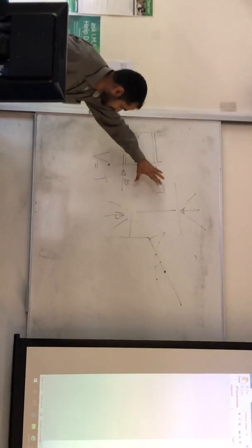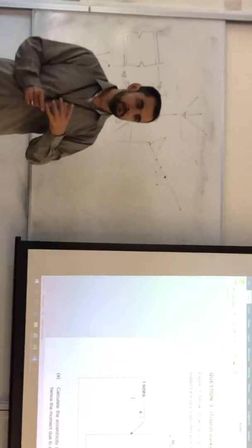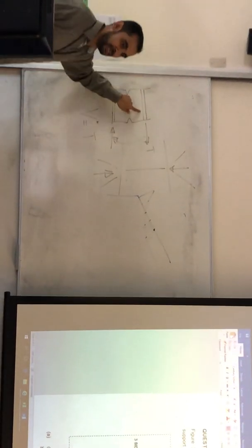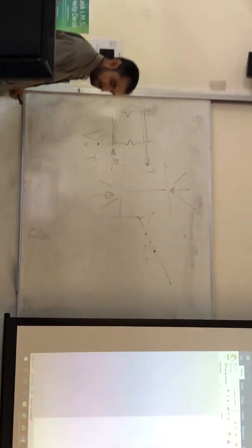So you find out that tension. Can your plate follow the load path? From the flange, it goes either to the weld. You either start from the weld or you start from the bolt.